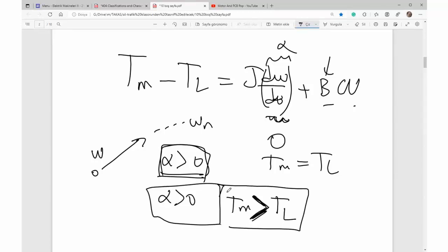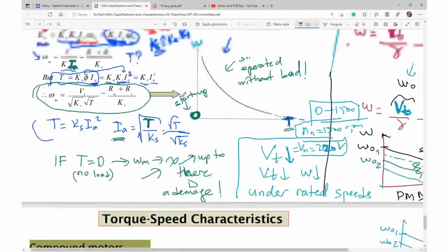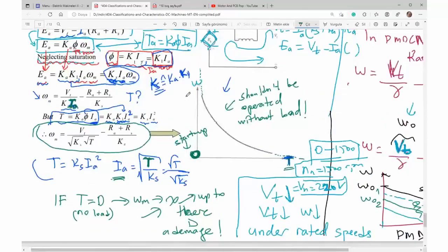So, in heavy loads, just like trains, locomotives, electric cars, forklifts, and some heavy instruments, drills for example, we use serial type motors. For example, for starting purposes in our automobiles today, we use a serial DC motor to start up the internal combustion engine. That is the starter motor of everyday automobiles.